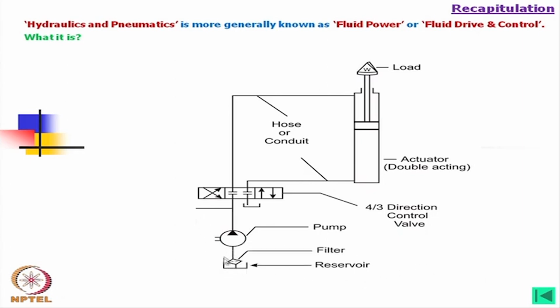We also need filtration of that oil, because we can pour the oil inside the reservoir after filtration, but each and every stroke this rod end is being exposed to the atmosphere, where it may catch dirt which will go inside, and that oil will be returned to this tank, and then it needs further filtration. Okay. So, this is called a strainer. Now, next we need a motor to drive this pump. Also we need a safety valve, which is a pressure relief valve.